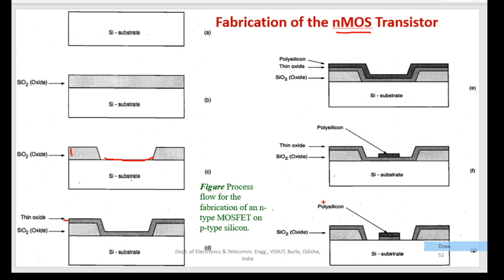But anyways, this polysilicon layer is again patterned to get this kind of structure. Now we have here this polysilicon, then this oxide, and then this semiconductor. This polysilicon is made to conduct, so it will act as a conductor. So it is like a metal in between oxide and semiconductor. So this forms a MOS structure, metal oxide semiconductor, right? And look here, this is patterned, so we get rid of the unwanted polysilicon layer and we get the clear MOS structure here, metal oxide semiconductor.